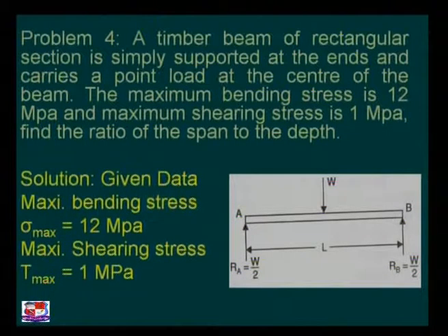shear force, but it is given to us that the maximum bending stress permitted in this is 12 Newton per mm square, that is sigma max is 12, while tau max permitted is 1 megapascal. It means precisely that if the bending stress comes beyond 12, my beam will fail, or if shear stress goes beyond one, my beam will fail. So, if we proceed further, then